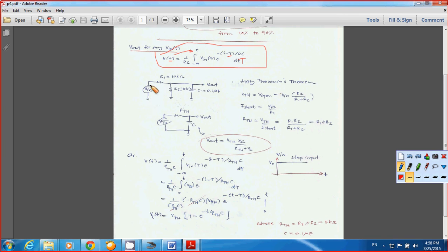Let's take a look at the circuit here. You might see it's complicated and you're not familiar with it, but in Basic Electronics 1 series, I already mentioned the Thevenin theorem. You consider this one as the load, and you have R1 and R2, and this part simply becomes the source, the black box of the source voltage. What you can do is convert this circuit by using the Thevenin theorem. Make the input only VTH, and then you have only RTH left, and you connect the load to the circuit here.